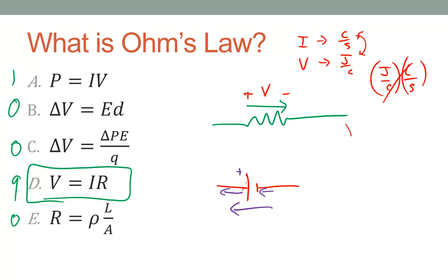But yes, like that. So in this case, notice I had plus and minus reverse from what it was on a resistor. And that tells me, oh, it's supplying power. You can charge a battery. You charge a battery by forcing the current to go the other direction through the battery. That forces the chemical reactions to run in reverse, if you have a battery whose chemical reactions can be forced to run in reverse.